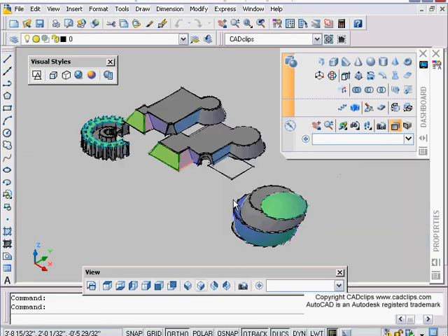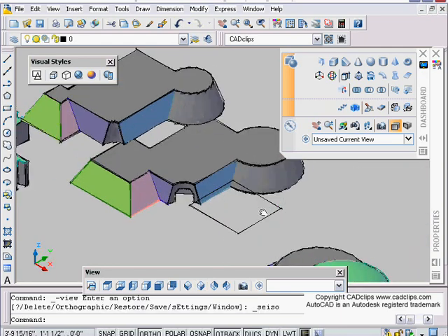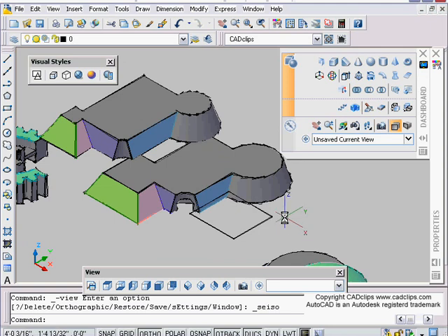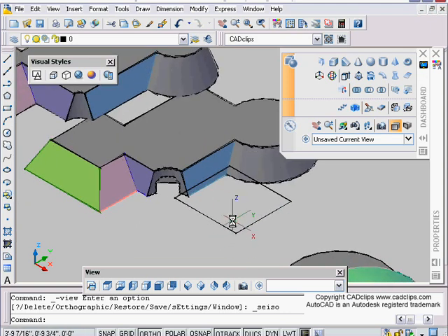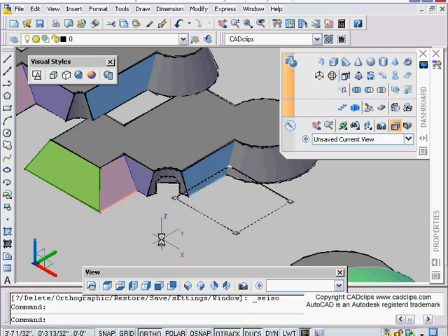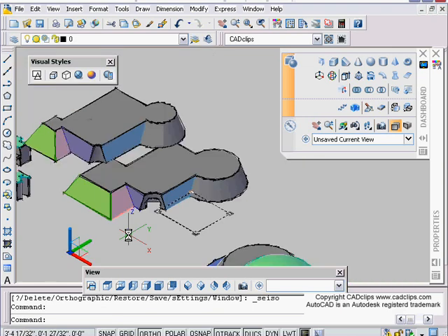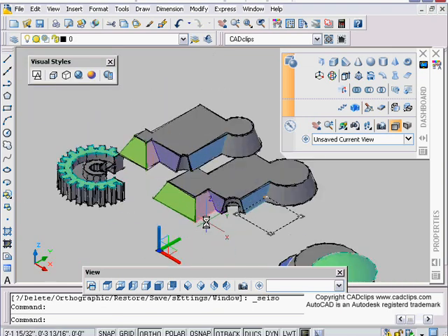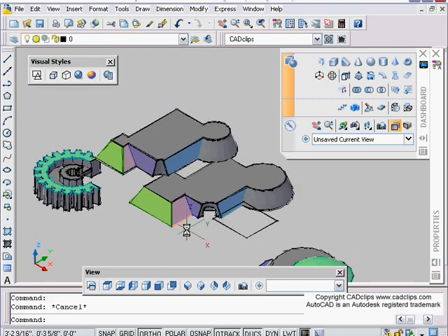So I have to admit, slicing by object can be quite challenging at times. The main thing is draw the object on one plane, switch to a perpendicular view, and move that plane up and down. And when you do the slice, I recommend resetting your UCS to the plane that the slicing plane was drawn on. So a couple little extra tips there. And once again, as a prerequisite, have a look at our previous 3D videos for AutoCAD 2006.